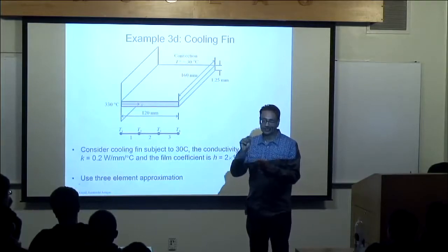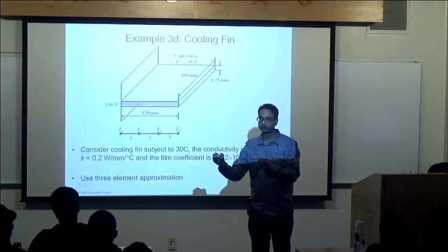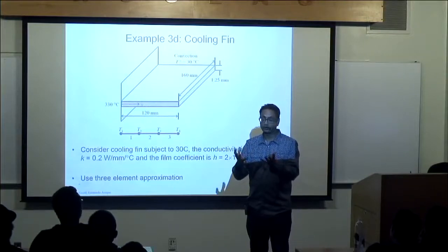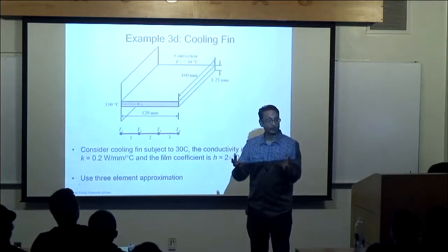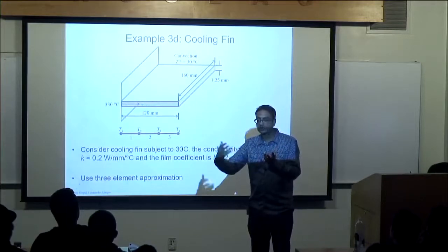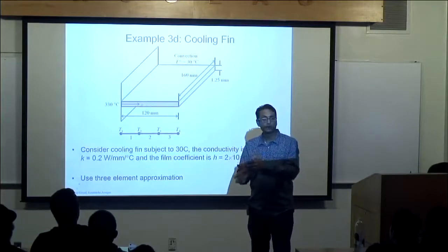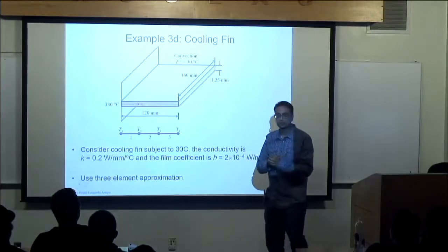It gives you the velocity of the fluid. It tells you the properties of the fluid. And with that information, they're able to tell you what the heat transfer coefficient is. Okay? Or if you have a capsule, a space capsule re-entering Earth. Well, I know the computational fluid dynamics from there. I know the velocities. I know the pressures acting on the surfaces. And I can do experiments to calculate what these heat transfer coefficients are, too. You can either determine that experimentally or make some estimations, right? But H is a property of that fluid, okay?